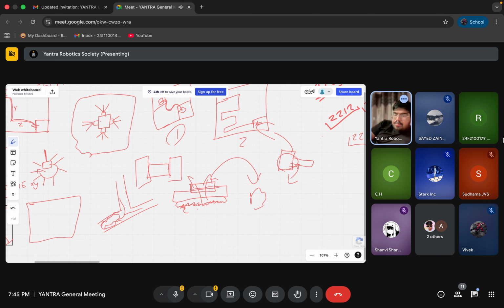That thing is there. Right now I think you'd have come with the F743, yes, some number is there. I don't remember the specific number, but yeah. Anything higher than 22. If you want to go for F7, go for something other than 22. That's my recommendation, because the F722 is kind of at the end of its life cycle.